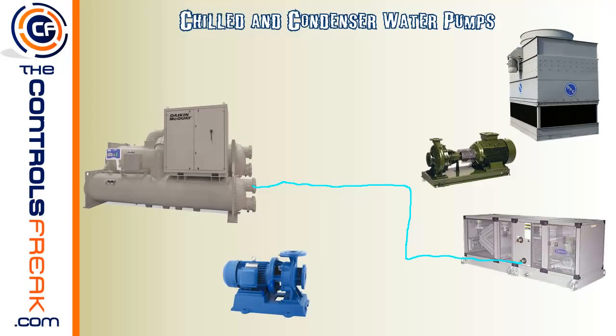of the coil. And the reason why is you want this to fill up with water before trying to pull it out. It's possible if you were to supply this coil with water coming into the coil from this direction, that the water may not actually fill the coil and you'll get air in this coil, which would mean that you're not going to get cooling on the upper portions of this coil if there was just air there, and water would flow in and then come down and get sucked out the bottom. So the reason why they fill it up from the bottom is that way you make sure you pressurize the coil and get all the air out of that coil. Alright, so we've got the chilled water coming in at the bottom of the coil.